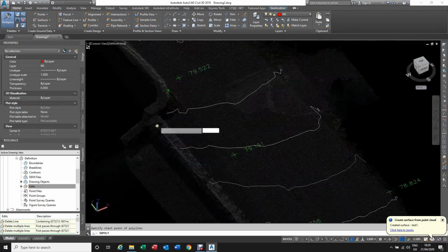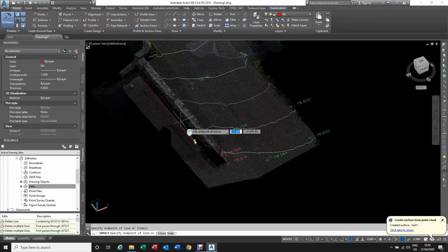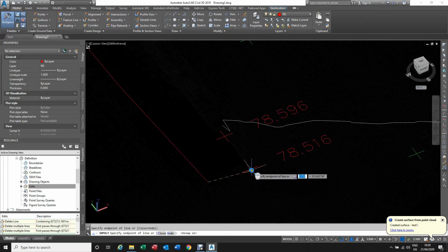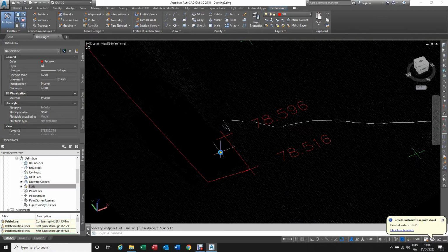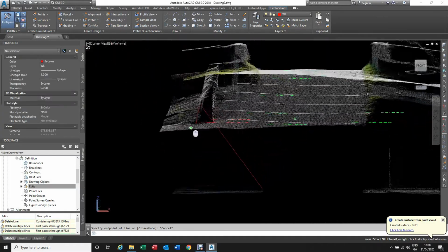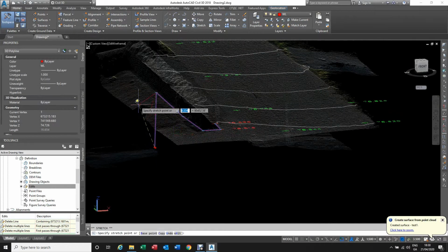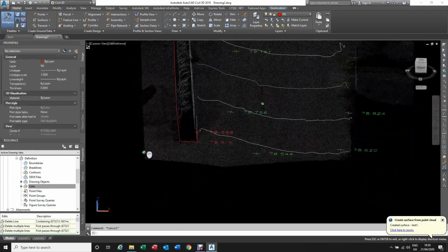If you turn on snap-on for objects and turn off F4 snap-on on point cloud, then you can just connect it to there. So what we made here is just a 3D polyline, and you see that's not really good here. Just bringing up F4 somewhere here. This is better now.